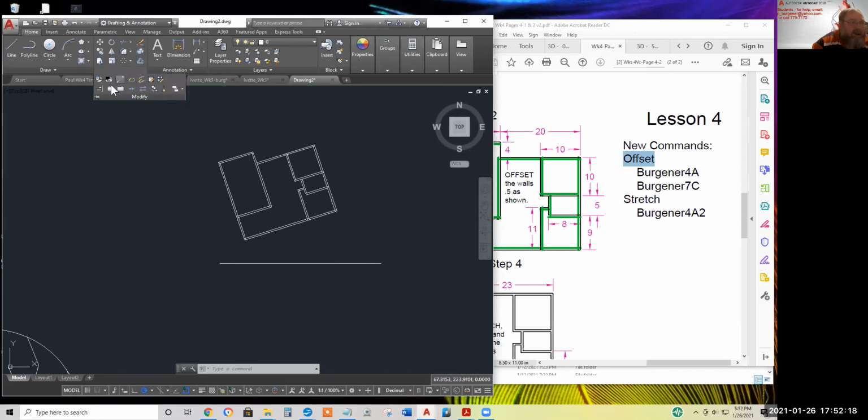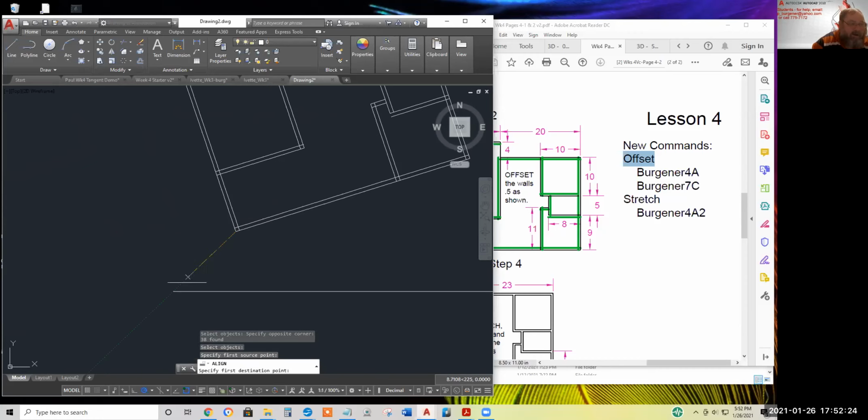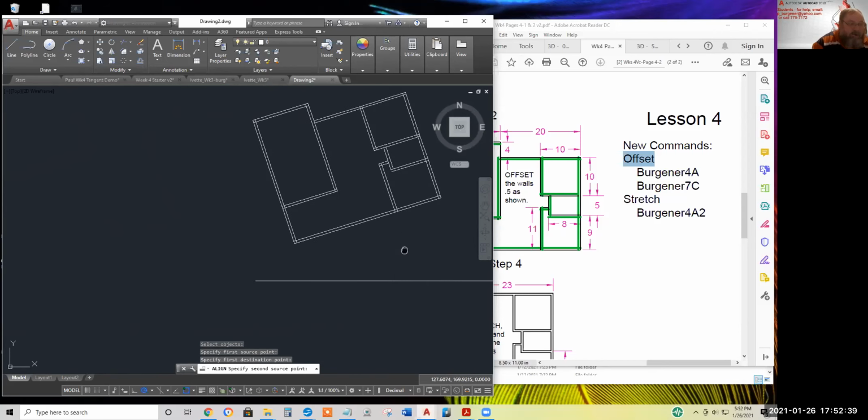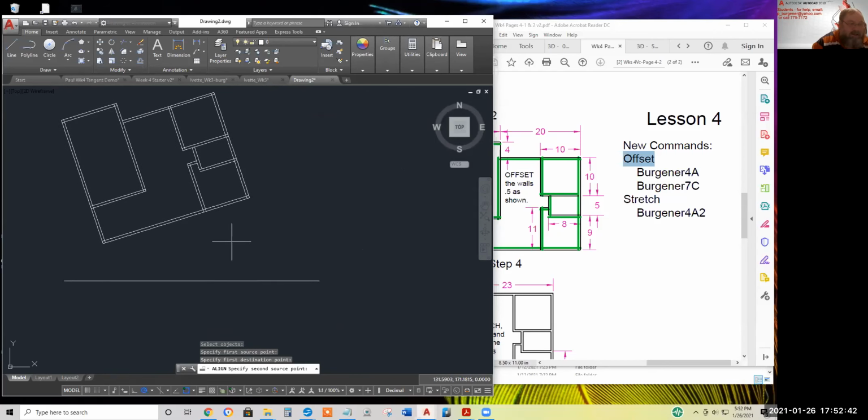Okay, getting back to the align command, we'll select everything. Hit enter. I'll O-snap there and I'll set a bungee cord. I guess I polar tracked when I moved it. We'll O-snap that at that endpoint or the intersection of the polar tracking and the existing line. Now it asks for the second source point and the second destination. As soon as you move, it disappears. Not sure why, but it still works.